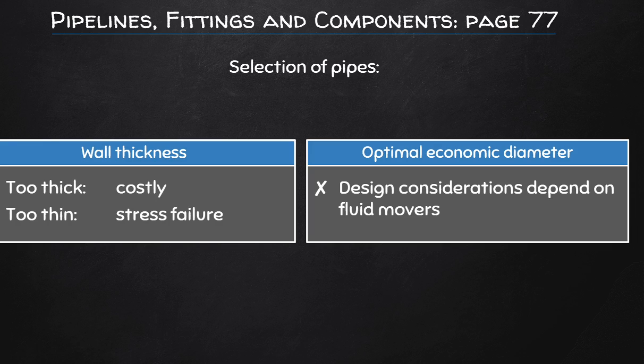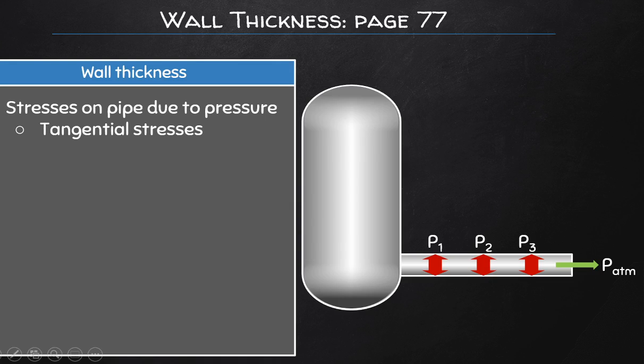You do find when you're selecting a pipe diameter, the suppliers of the pipes give you some correlation that you can use to determine the maximum yield stresses for those pipes at certain elevated pressures, and so they can tell you what the maximum pressures are that you can operate at under certain temperatures of operation. Now, the stresses placed on the walls of the pipes originate firstly from the static pressure of the fluid.